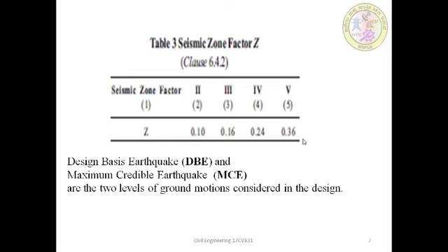The ductility of the structure will give enough warning before the failure. The level 2 design allows the structures to have significant ductility, such that even under a bigger earthquake, the structure provides sufficient time before the collapse. The best design is one in which the occupants can come out of the building and see how the structure is falling. Hence, the concept of different levels of design is extremely important in earthquake resistance analysis.